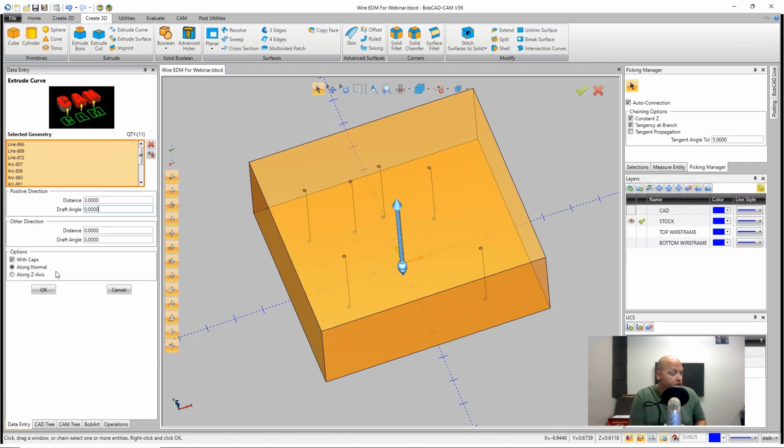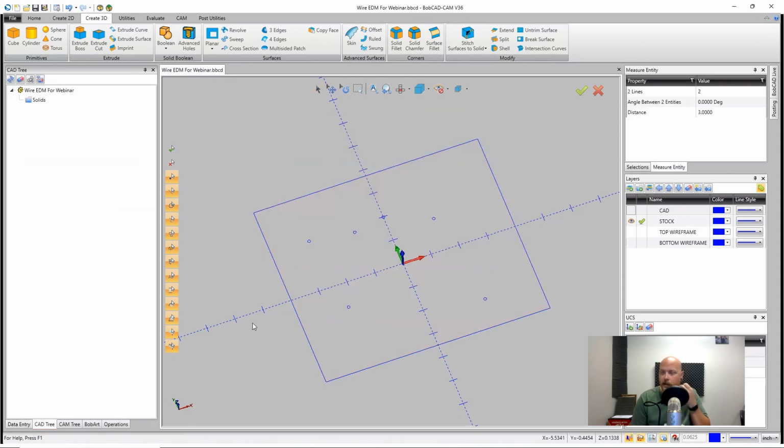When we go to pick stock, we could either use rectangular stock, we can use wireframe stock, or we can use a solid stock. I'm going to go with wireframe or solid on this because I have holes punched in this already where I went in and lined up where I would put some holes. So this stock represents the holes. It gives me a good place to start all of my tool paths from, and it just helps to have those ones. Now, if you don't add the holes in, but you know where they're going to be positioned, that's fine too. You just won't see the hole inside the stock. I'm going to keep it as wireframe because I don't see a lot of people using the wireframe stock too often, and it's a really good option.